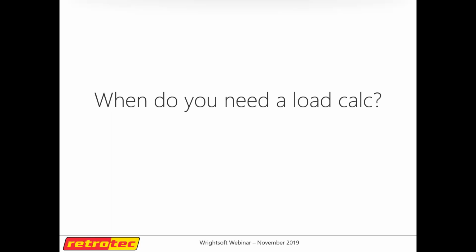I guess the biggest uphill battle that we're constantly fighting is contractors that are wanting to use a rule of thumb for sizing. So if it's a ton per 500 or 600 square feet, it's not that easy. There's so many variables to determine what size system you need in a house, and you have to do a load calc in order to get that right every time.